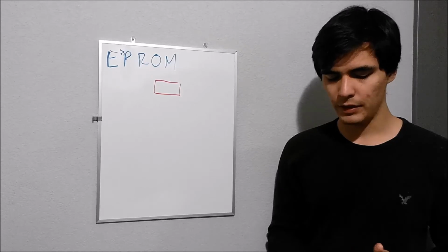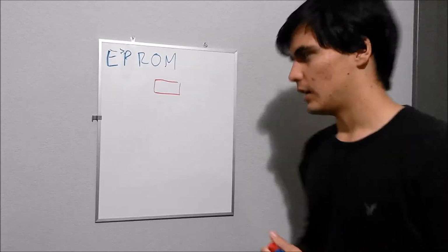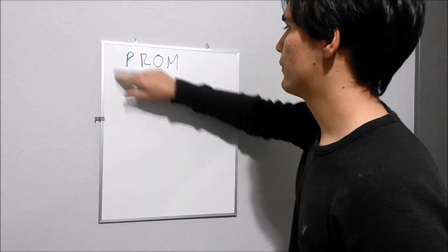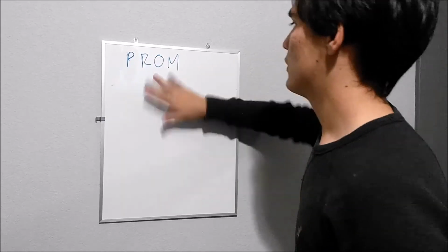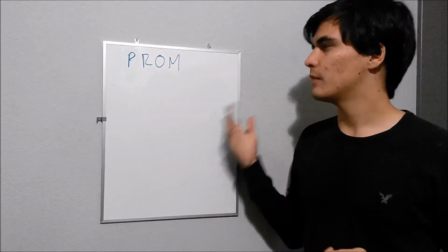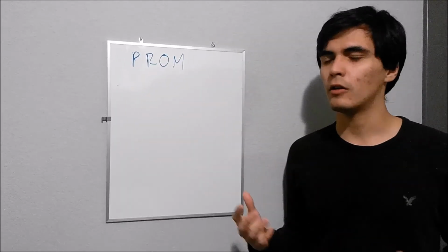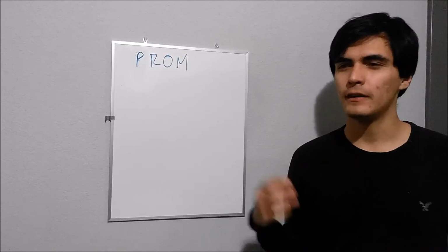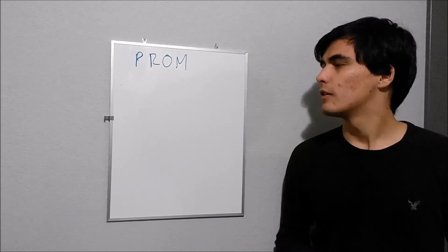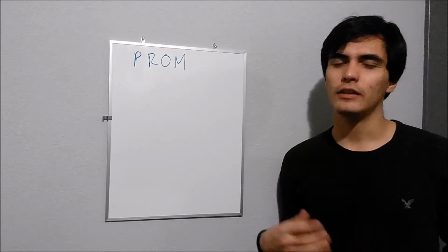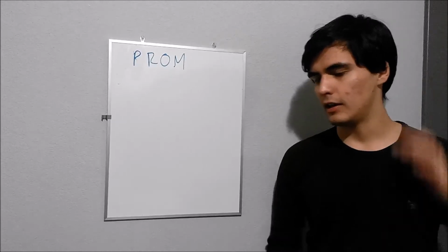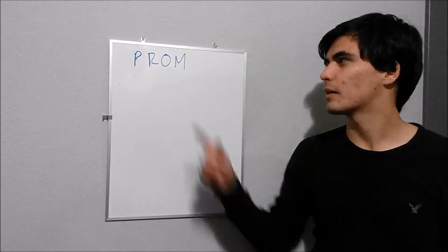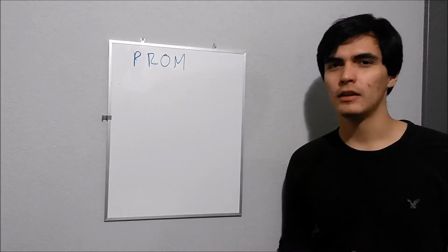So to work with the PLD, a PLD works like a PROM. The PLD is an array of AND gates in the inputs and fixed connections in the outputs. So the AND array in the inputs, you can program it like a PROM because they have fuses.